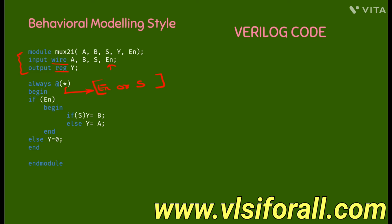So you can always replace this star with this so that it becomes more clear how the multiplexer works. Followed by this, we write the begin statement, and since the behavioral modeling style in Verilog is very similar to software programming, we always use statements like if, else, case, etc. to write down our codes. This part of the code, the always block, is the black box that we've already studied, where we need to put in the functionality.